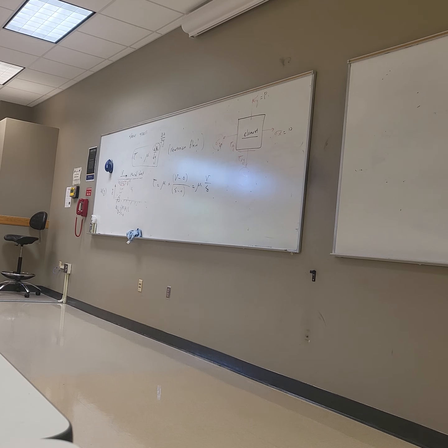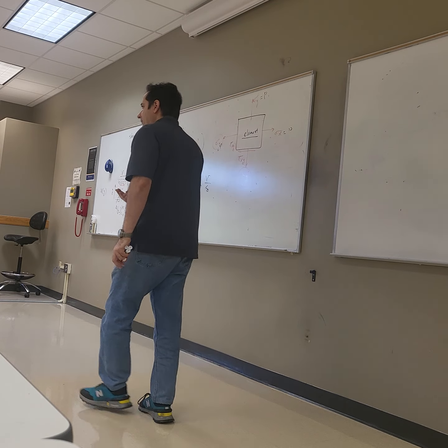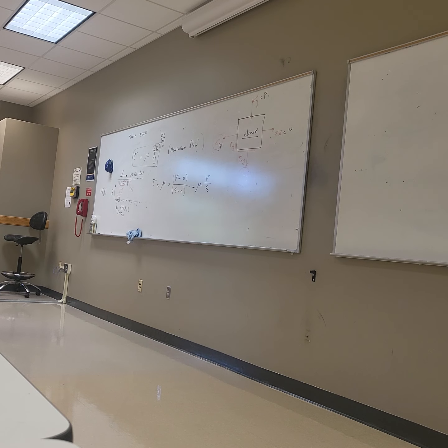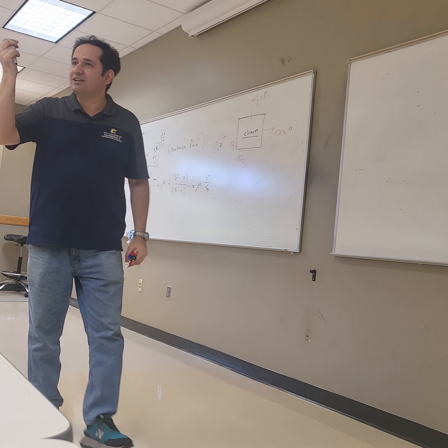We'll talk about it in the video. And depending on how your fluid is moving, if the fluid is moving in a laminar way, that means you have laminates just rolling on top of each other. It's called laminar flow. But if the fluid becomes chaotic and all those particles hit each other and move chaotically, we call it turbulent flow, and the shear stress will increase.